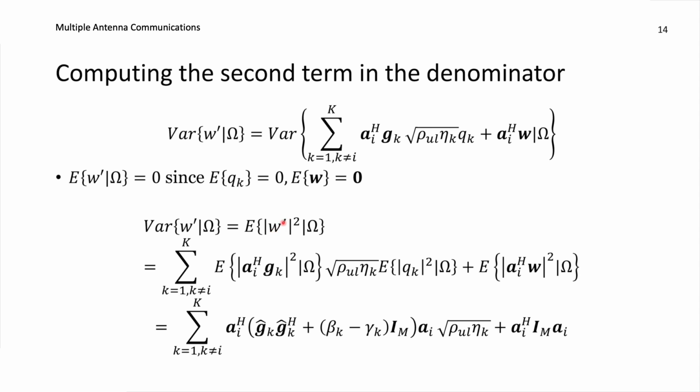And when we are computing something like this, we have multiple terms here, and computing the expectation of it would be to compute the expectation of each term in absolute value square, and computing the expected value of cross terms when we take, for example, one of the user terms and the noise term, or these user terms for two different users, and multiply them together, one with the conjugate. And all of those cross terms are going to be 0 because we have 0 mean on all of these types of randomnesses.